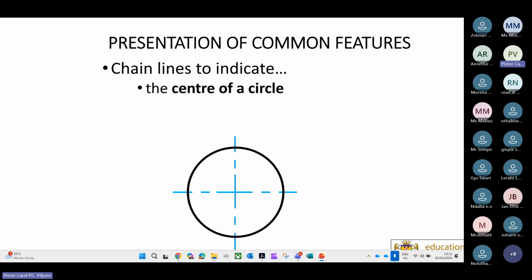If you go to any hole drilled into an assembly drawing, any cylindrical object, any nut, any bolt, any shaft, there are a lot of center lines. So this is very important to show the learners, because learners are losing a lot of marks. Last year it was with the analytical question, with the cams, with the isometric drawing where there was a circle involved, and there was mechanical drawing. So in the vicinity of 4, 5, 6 marks learners lost because they don't put in center lines.